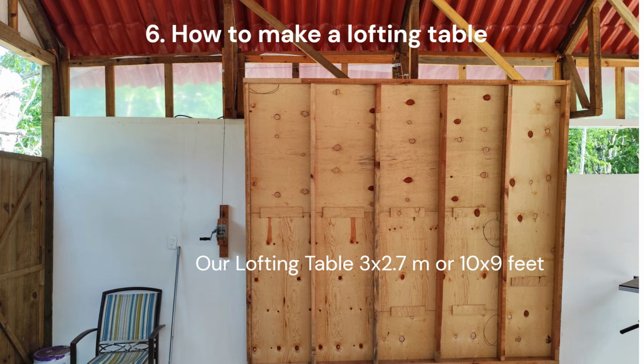Our lofting table in the picture is 3 by 2.7 meters, 10 by 9 feet, and made of wood frames of 40 by 75 millimeters, 1.6 by 3 inches, plus surrounding beams. On top of this is 12 millimeter plywood, screwed with Spax torque screws. The plywood edges are filled with something called ready mix and sanded. The table is painted with 3 layers of white paint. Calculated, the total weight of this table is about 70 kilograms. The lifting device is accomplished by a 300 kilogram winch and 4 pulleys.